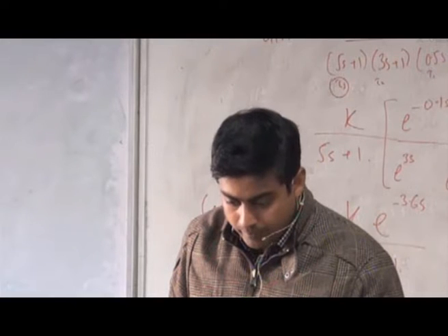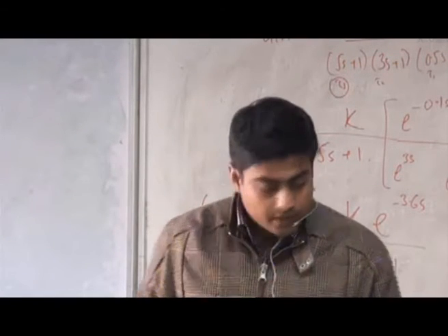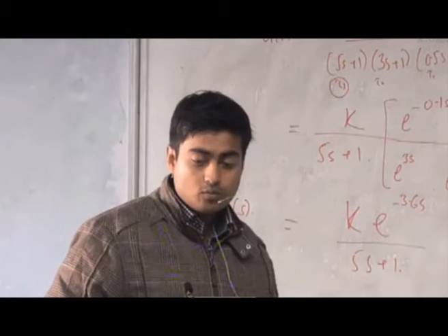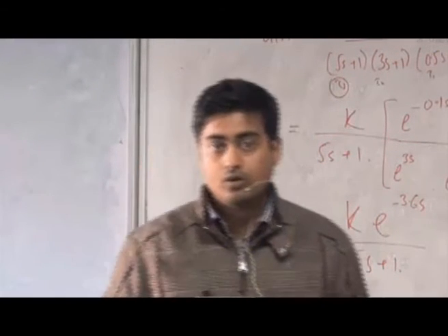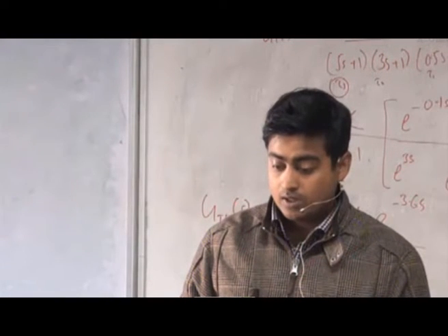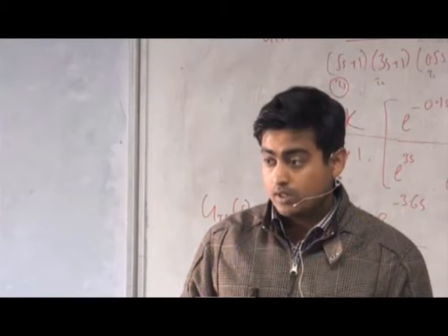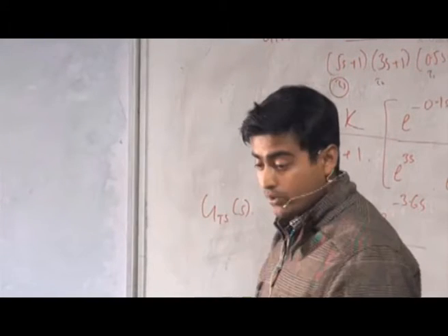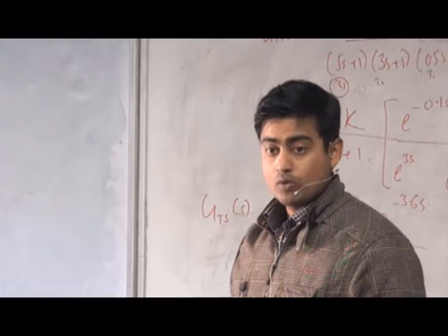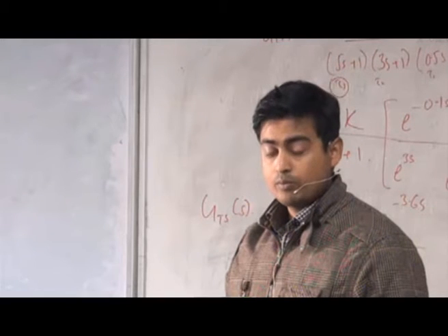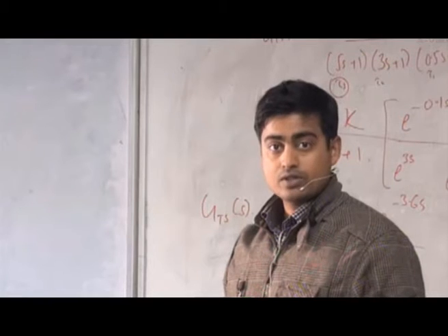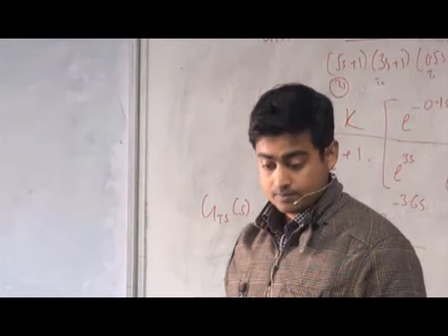For a higher value of time delay, it is almost a similar procedure you will follow, whatever we have done for the first order and second order system, that you need to approximate it to a lower order one. Then either you could, like I said, use the lower one by one paired approximation where you add one zero or one pole. Okay, and then you start doing your analysis in the same way we have done for the first order and second order and pole lead lag systems.